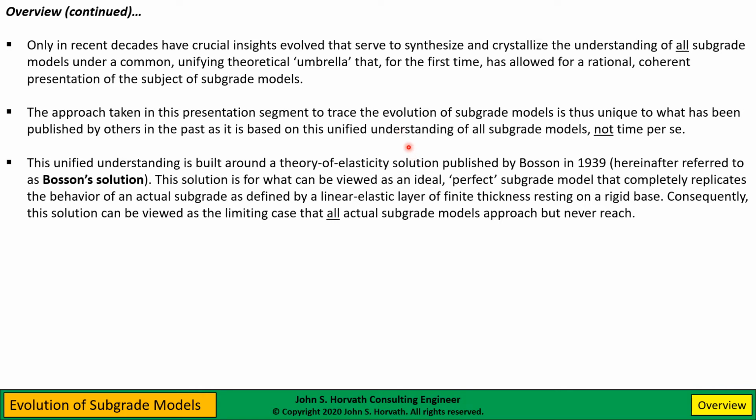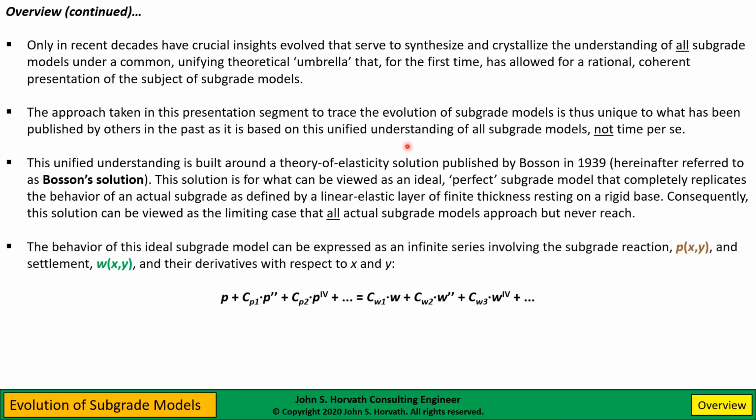And what was interesting is the way he presented the solution was as infinite series. So it was an infinite series involving the subgrade reaction P and multiple derivatives of P. And again, this second derivative, fourth derivative, I'm using this shorthand. And an infinite series of settlement.